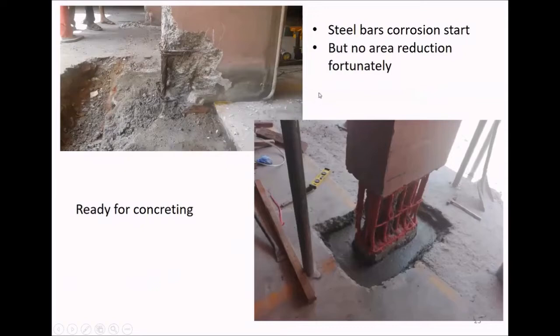We had good supports to the beams, slabs, and everywhere we provide supports, and we break the concrete, we remove up to this level, and we do the necessary painting of reinforcement bars, and we did grout filling of this area. That is the way that we have done this rectification.